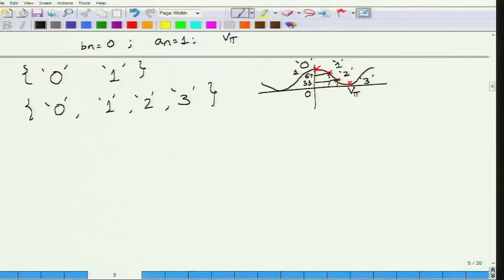Now, how do I obtain 33% transmission? I simply go back to this expression cos square pi V divided by 2 V pi, and then say this value should be equal to 0.33 for 33% or 0.67 for 67%, and it should be equal to 1. For 1 you know what is the value. So, find out what should be V by inverting this relationship, right.